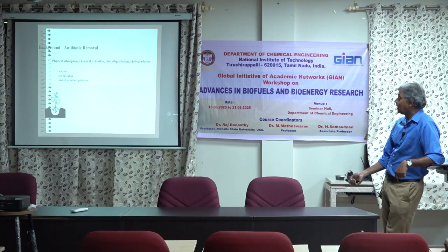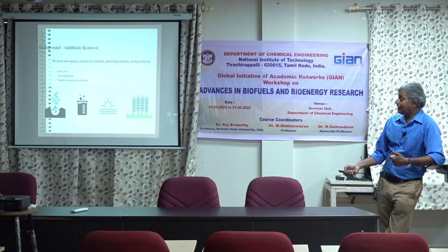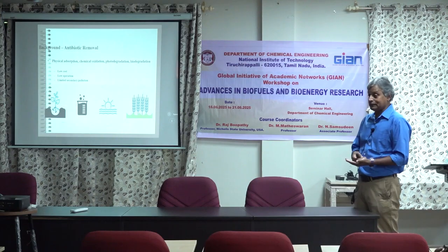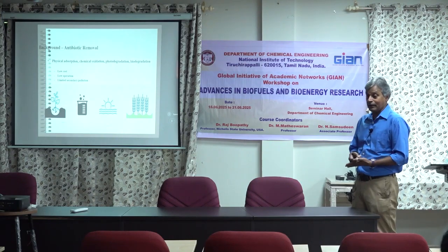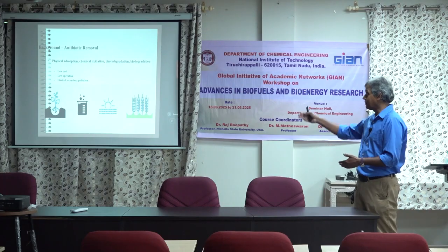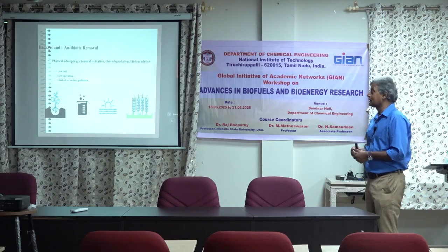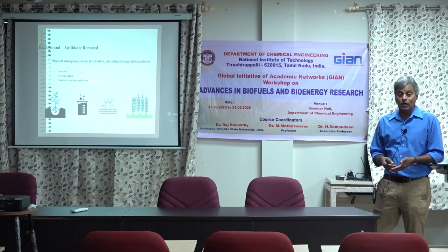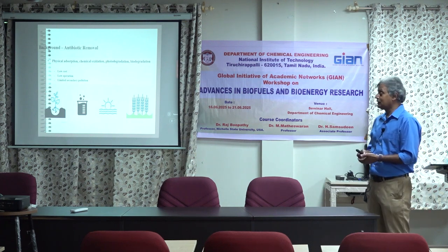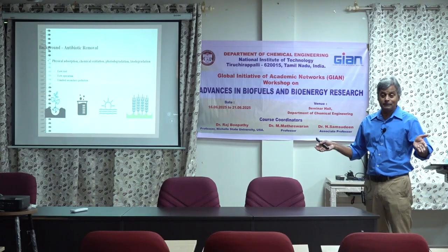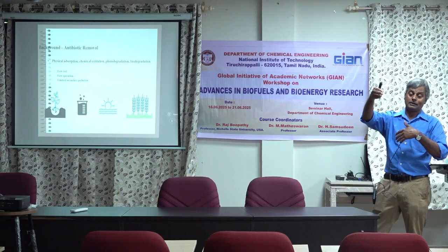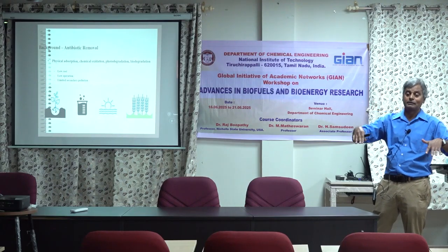Okay. So what is happening in the wetland? There is physical absorption, chemical oxidation, photodegradation, biodegradation, all the phenomena happening in one place, right? That's why it can take out these emerging contaminants. Operation-wise it is low cost, low operation and maintenance, and has limited secondary pollution, because all you're doing is letting the water go through the wetland and come out the other end, and the algae, bacteria, and plants take care of this. Okay.